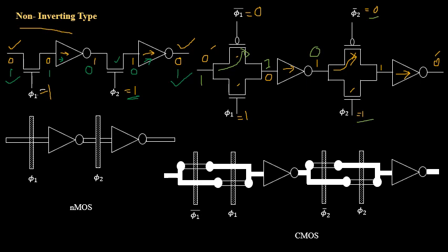Next, 0 is passed through this particular NMOS transistor, so that I am getting the exact logical 0 state. It can pass through the PMOS also, but it won't give me exact 0; I will be obtaining 0 minus VTP. 0 is passed through an inverter and it will yield me the output of 1. So I have applied the input as 1 and I have obtained the output value as 1.